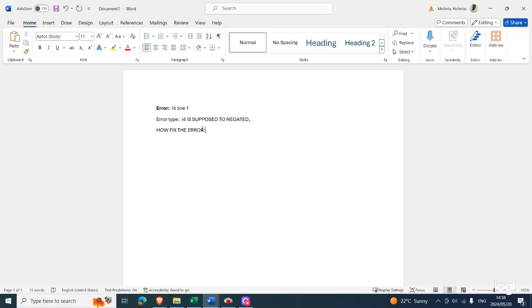One thing that I want you to use in your explanations is the state of your contact and your output. So you're going to say I4 is normally open or normally closed, whatnot. If you put it in the circuit like this, this will happen. That's why, when you put it in, you have to negate it so current flows or doesn't flow. Your explanation should be centered around the state of the input, and also why you're negating it or not negating it. This is what I expect to see when I'm reading through how you address the code.